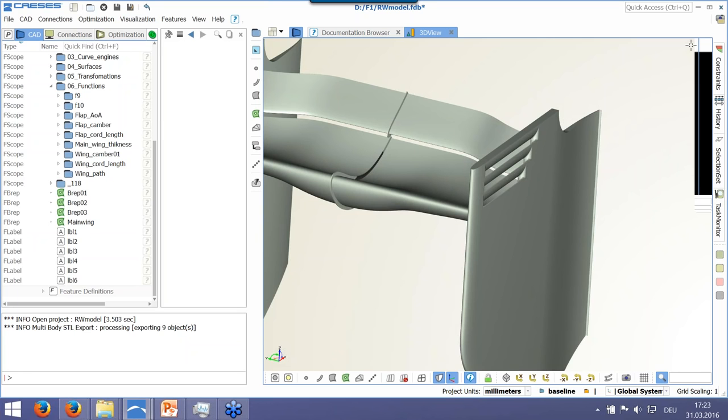I will not go into more detail, but this vector of velocity will change the downforce vector, and this vector will have a component to drag. So they call it induced drag because it's generated in a way by the downforce vector, due to this velocity created by the vortices, so the downwash.